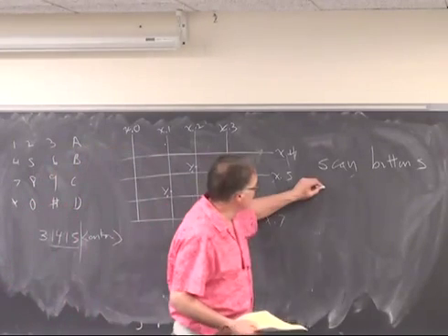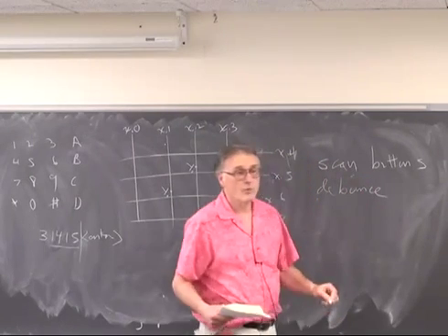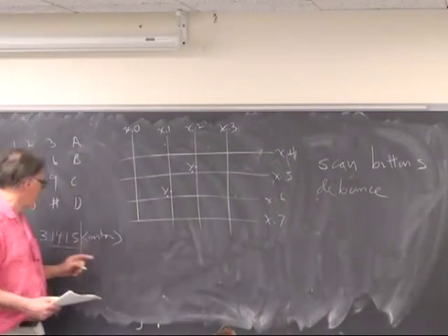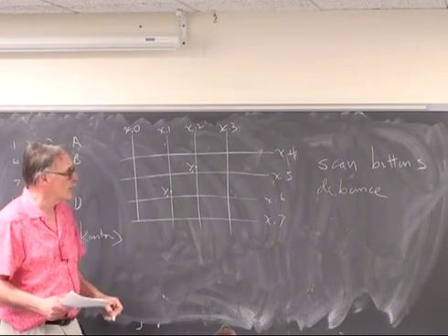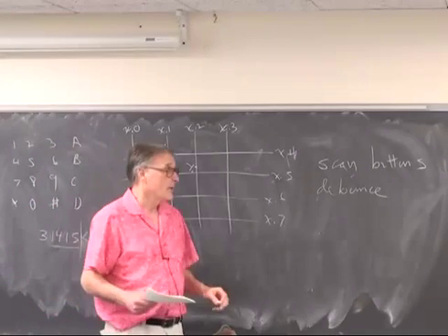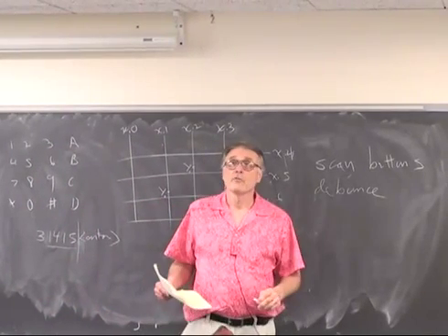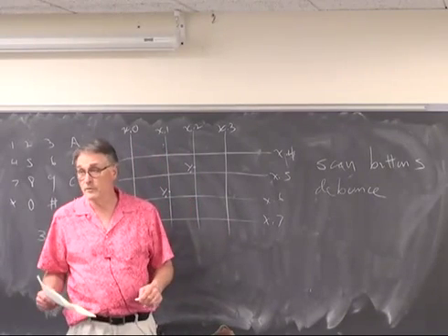And of course, we have to debounce, because nobody wants to have 333114444 and so on in the number that comes out. So you have to debounce. That's actually more important for Lab 3 than Lab 2, but it is important for Lab 2.